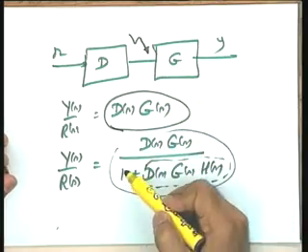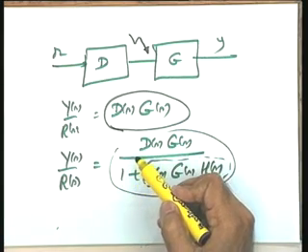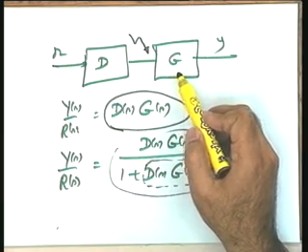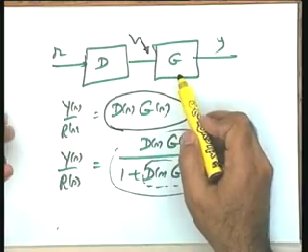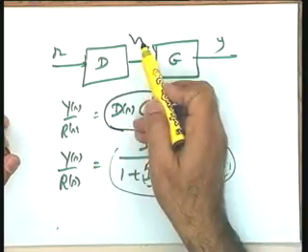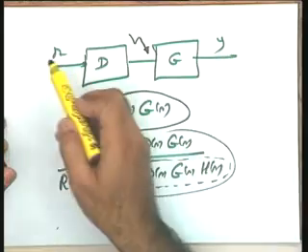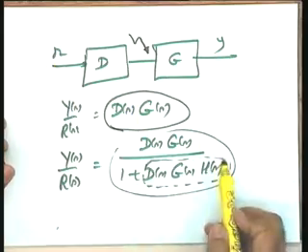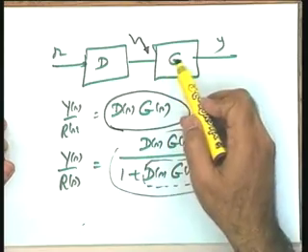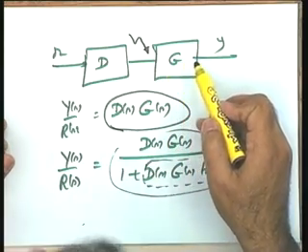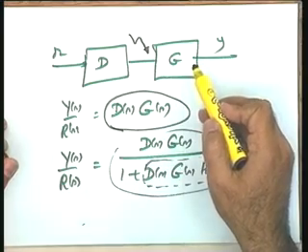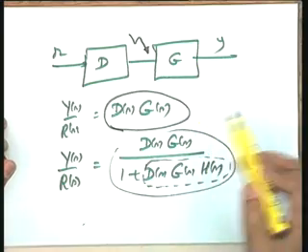For the feedback action, the only precaution I can take is to adjust the plant so that the gain of G is higher, because I know that when I connect a feedback loop the gain between Y and R will be reduced. To bring it to acceptable limits I can make certain adjustments on the plant model G, and this is the way I can accommodate for this loss.